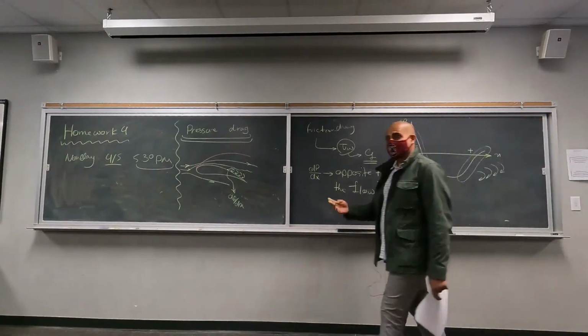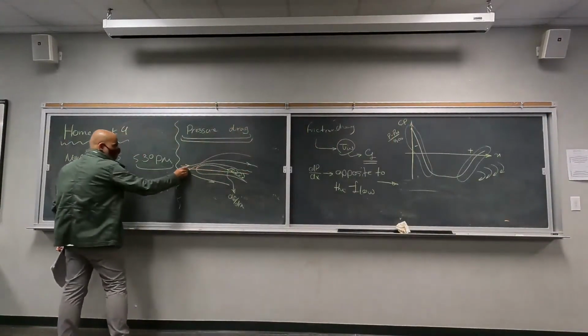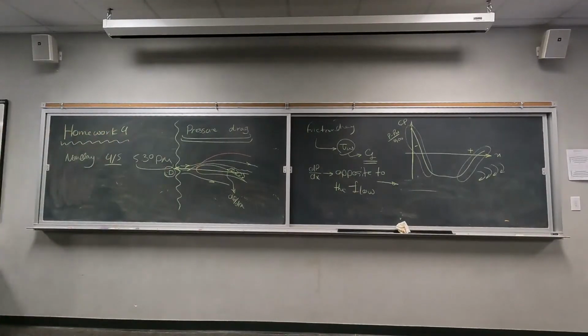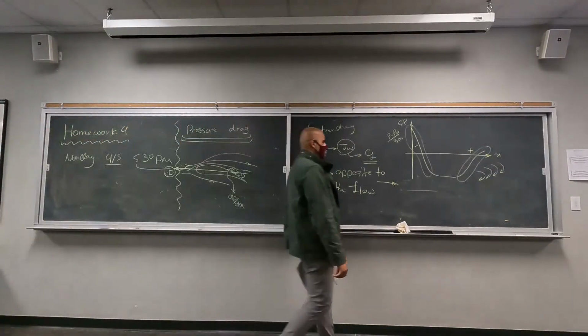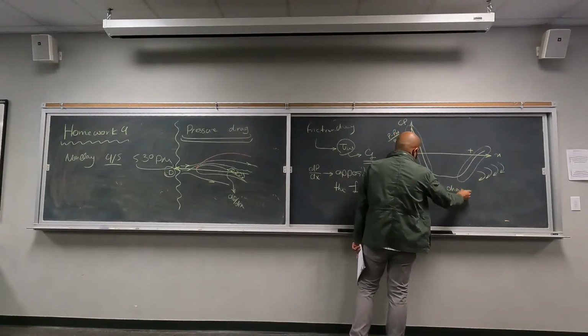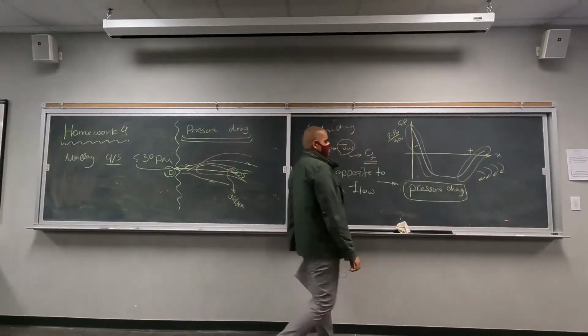So what does it mean for the forces in the direction of the drag? It means there is some part of the flow that is pushing the airfoil against the real flow, right? Will the drag increase? The drag will increase. That's the idea. And this increase in drag is all attributed to pressure drag. Pressure drag is there, or increases, because of the adverse pressure gradient.